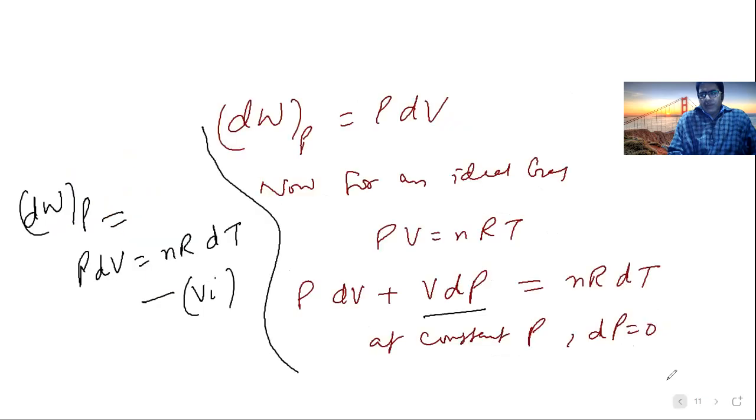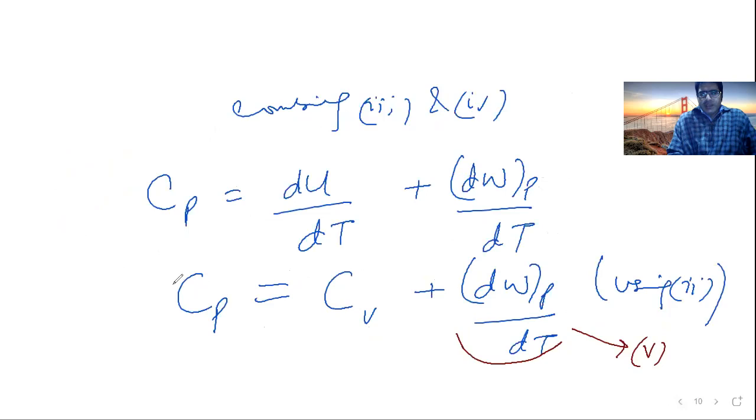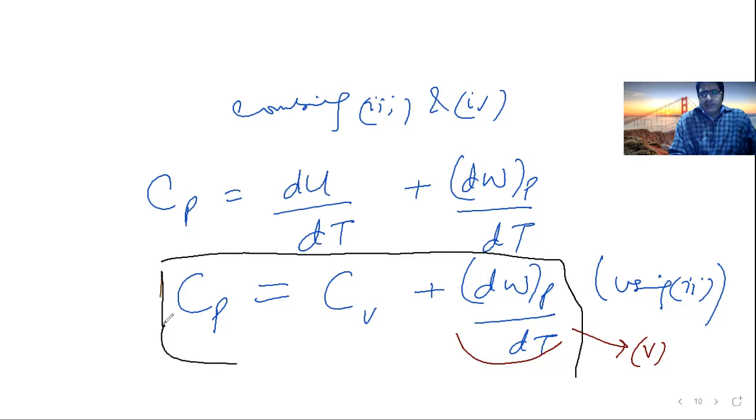But this equation, as I have already discussed, this equation is valid for any system. Now for solids, when we heat a solid, it expands very little. Therefore, this term, the work done by the system at constant pressure, because it involves change in volume, is negligible, since solids expand little on heating.